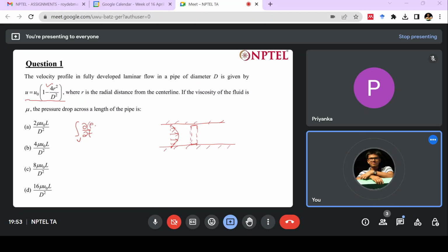Let's say we are talking about our x direction momentum, in this direction. This is our temporal derivative, the volume integral. If any momentum is getting generated inside the volume, since the velocity profile given is a steady profile, we do not really have any change with time. So this term will be zero.